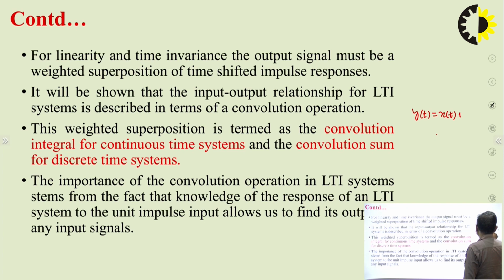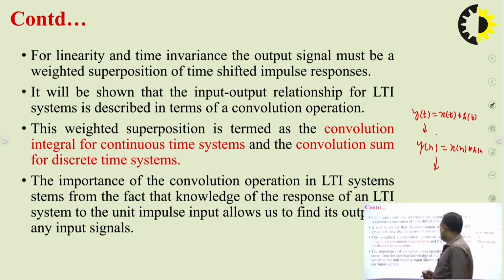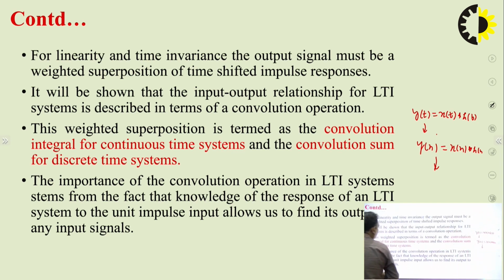When we do this for a continuous time system, the operation is called the convolution integral, and when we perform it for a discrete time system, it is called the convolution sum. The importance of the convolution operation in LTI systems comes from the fact that knowing the impulse response of an LTI system, its output to the unit impulse input, allows us to find its output to any input signal.